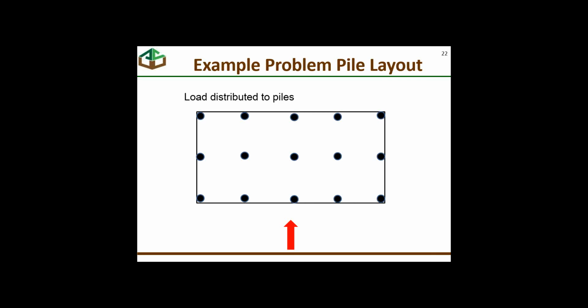And so that's basically what I assume when I do a foundation design. We also, in this particular building, have shear walls, and those shear walls are at the ends of the 40-foot long segment. And where we have those shear walls, we also need to make sure that that shear is taken out in the beam system and across those three piles.